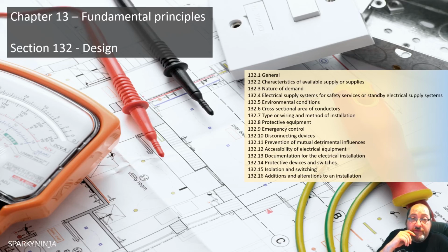But we must verify that if we add any demand, any impedances to an electrical system, that the existing protective measure, whether it be ADS, double insulation, whatever, is sufficient, because it must be sufficient. If it's not, and we work on the system by increasing an impedance, even maybe decreasing an impedance, which would therefore increase a fault current, that could be a problem.